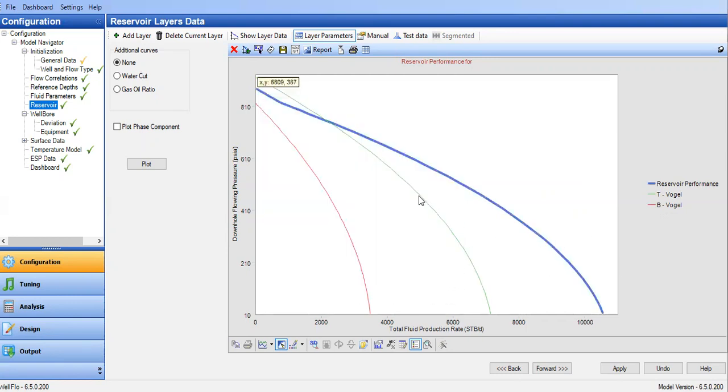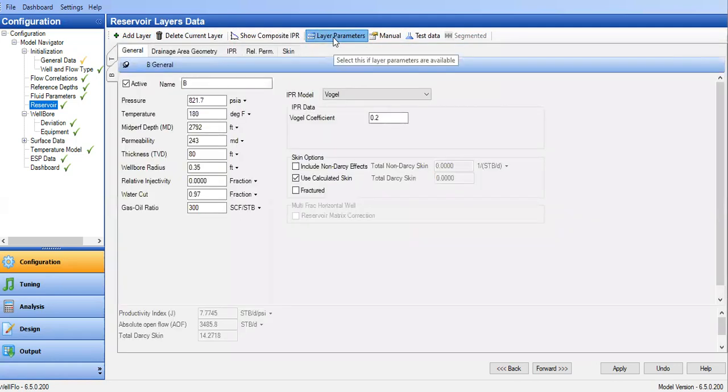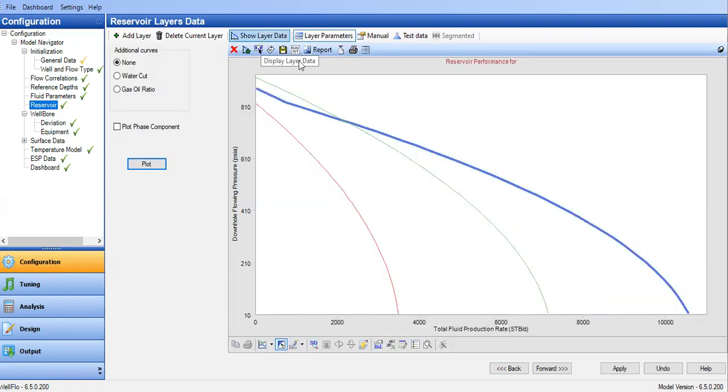Okay, so this is what you have if you perform commingled production. There is no risk of crossflow between the two reservoirs, so in general, you obtain a better performance. You get a better performance from a liquid production perspective. We still don't know about the oil production perspective because we have different water cut.